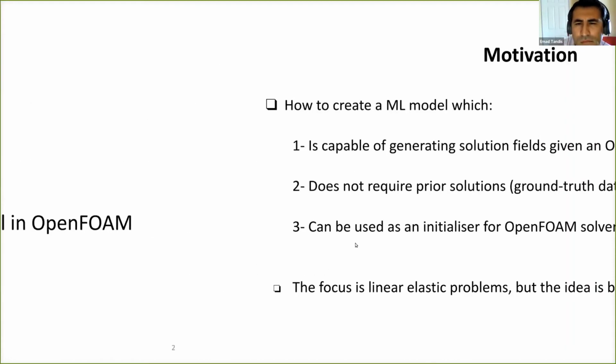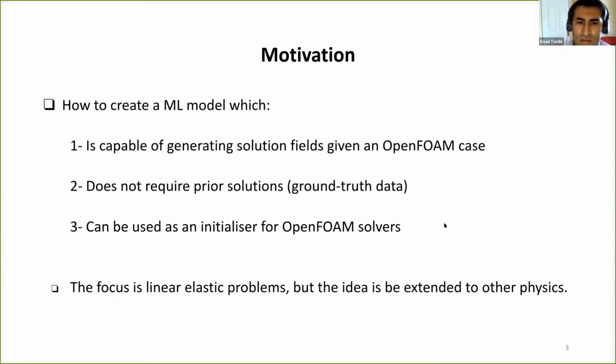The motivation here is we want to build a machine learning model which is capable of generating a solution field given an OpenFOAM case. And it does not require a prior solution, so it does not require ground truth data. And finally, we want to use it as an initializer for one of the linear elastic solvers in solids4foam. Here, the focus is linear elastic problems, but the idea can be extended to other physics as well.